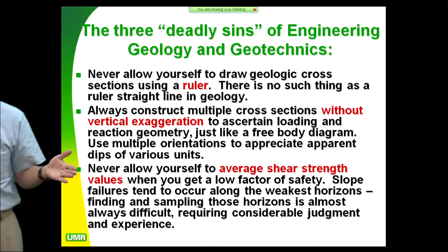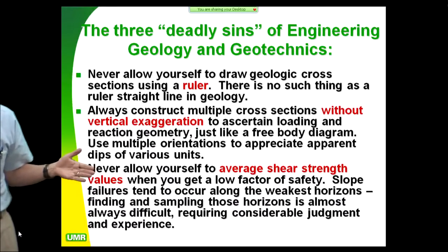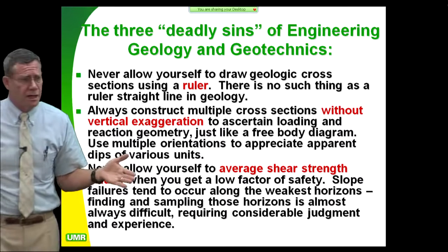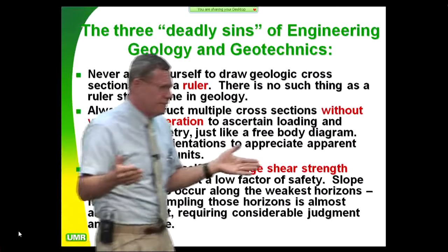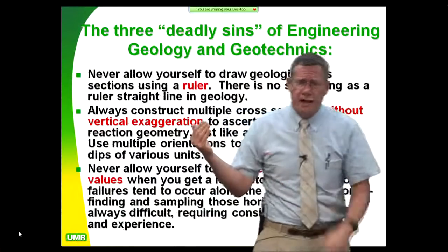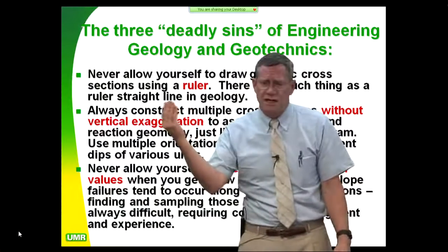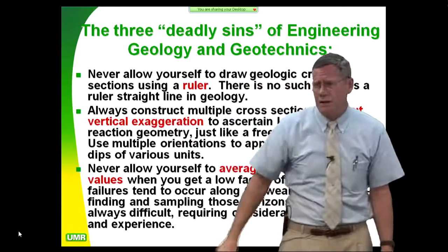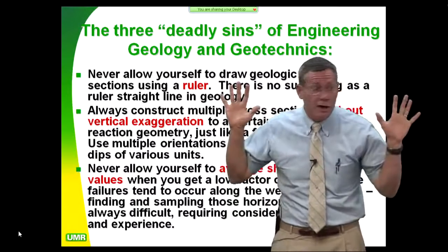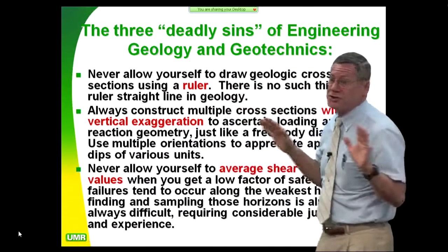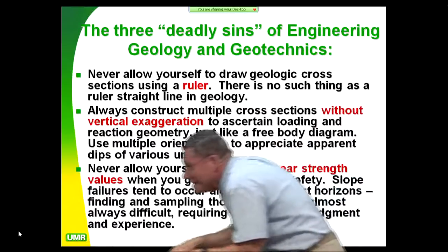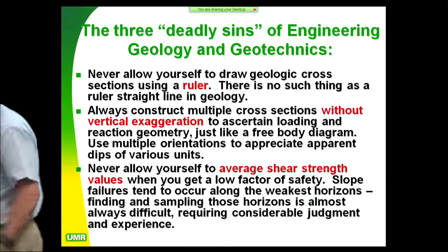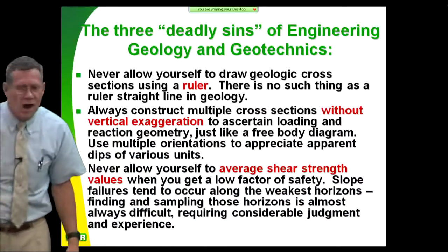It's like looking at a seepage analysis on a levee. If you go into the Corps manual, the office manual for levees, they always have the seepage cross-section 90 degrees to the levee. So all the water in the world is only supposed to seep under levees going perpendicular to the axis of the levee. Never does that. Ever. Ever.